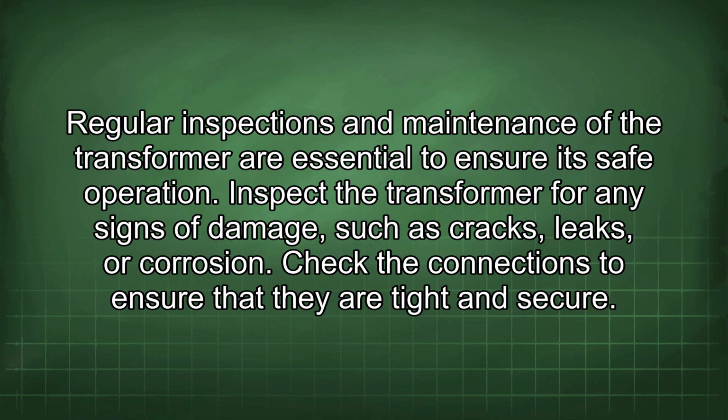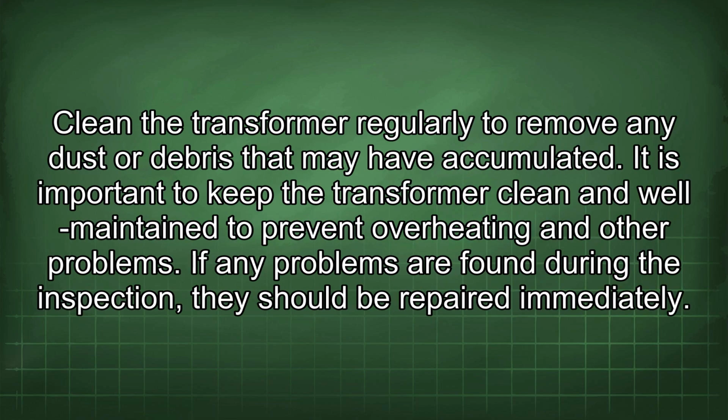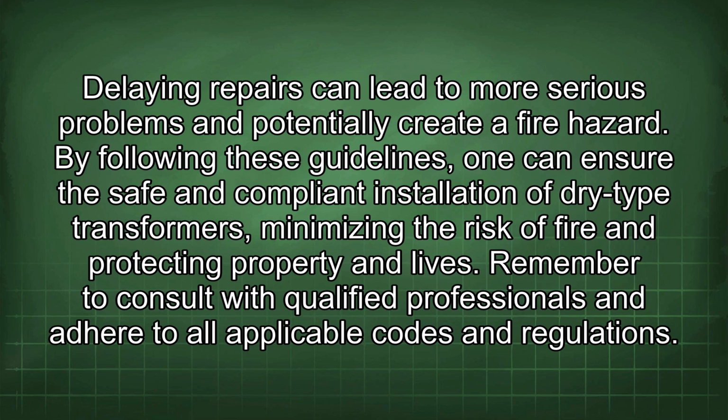Regular inspections and maintenance of the transformer are essential to ensure its safe operation. Inspect the transformer for any signs of damage, such as cracks, leaks, or corrosion. Check the connections to ensure that they are tight and secure. Clean the transformer regularly to remove any dust or debris that may have accumulated. It is important to keep the transformer clean and well maintained to prevent overheating and other problems. If any problems are found during the inspection, they should be repaired immediately. Delaying repairs can lead to more serious problems and potentially create a fire hazard.